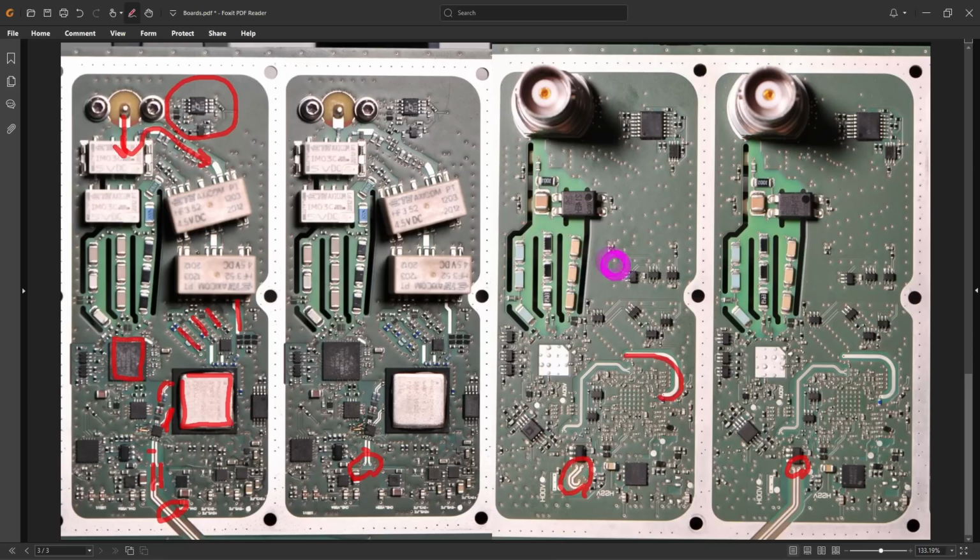A bunch of op amps and regulators and switches and analog muxes and all kinds of stuff are scattered around over here to control everything, but you can see what it takes to make a complex front end to feed high performance ADCs. The front end of oscilloscopes is a work of mixed signal design on its own.